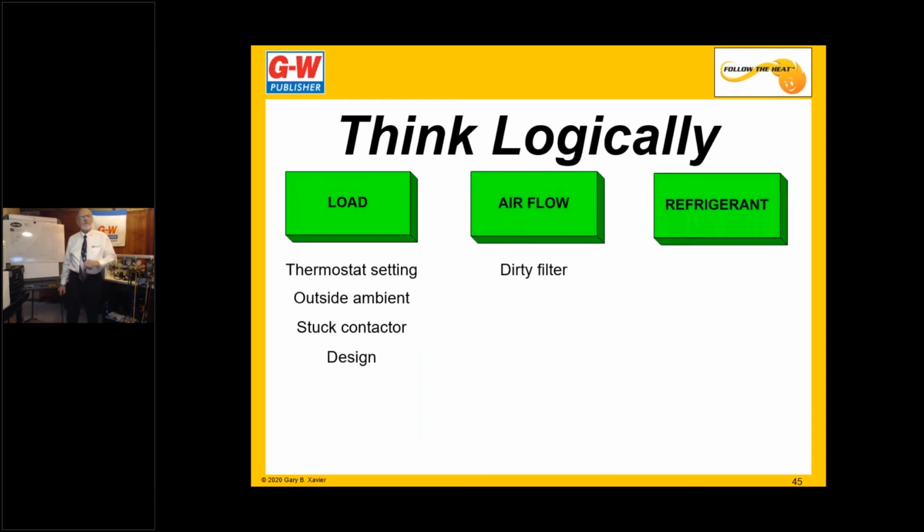And that gentleman said, well, when it gets sucked into the evaporator and covered with ice, it's probably time to change the filter. And he was making a joke, of course. He knew better. But I thought, wow, how many times have we seen that the filter is so dirty that it gets pulled into the coil and the whole thing ices up. Lack of airflow, dirty filter, number one cause of problems on our air conditioning system.